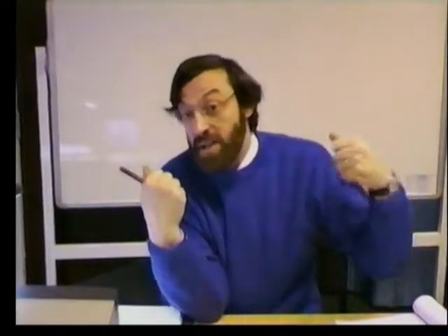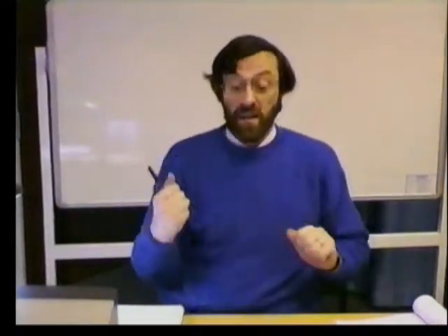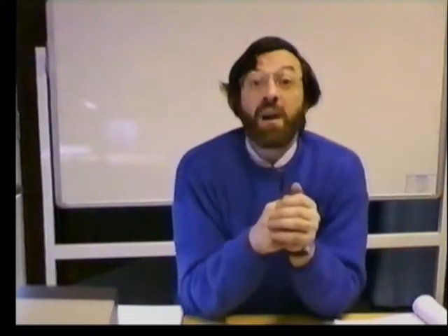Bear in mind, the way showers work is you don't have a variable heater. You always have a fixed heating element. It's like an electric fire: 3 kilowatts, 2 kilowatts, or 1 kilowatt. The way you vary the temperature of the water is by the amount of water you flow through it. If you want very hot water, you just trickle a little bit of water through the heating element, and then it gets very hot. If you want a much cooler shower, you pour more water through it.